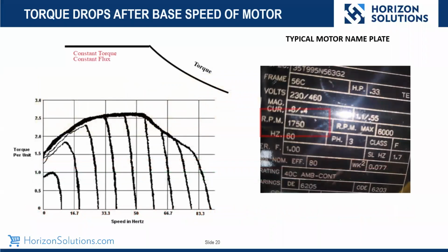Here's something Kevin and I get asked a lot. I'm looking at the nameplate, and I really don't know what I'm looking at. Let's take, for example, the RPM 1750 here. Now we're going to look at this and say, okay, I do meet the Class F. That's great. So now I have a standard 4-pole motor with 50 RPM slip. I'm rated for the 155 degree temperature. And now let's look at this.